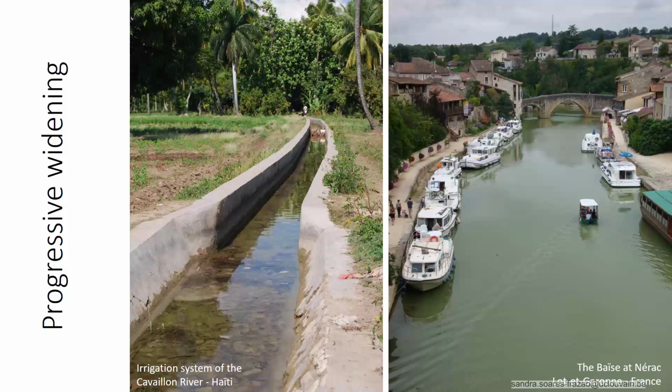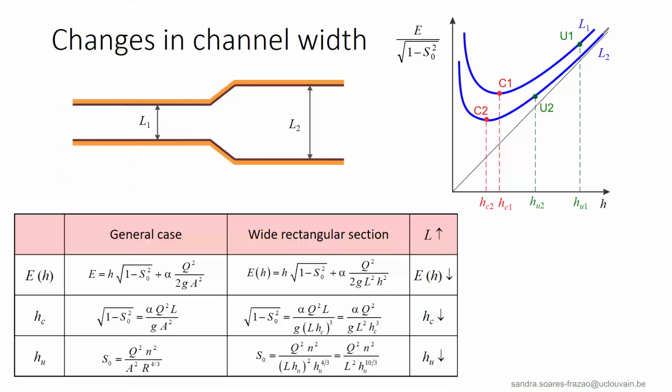Let us now consider a progressive channel widening. We can do the same analysis as the one conducted for a channel narrowing, and conclude in the present case that for a width L2 larger than L1, the specific energy for a given water depth will decrease, as well as the critical and normal depth. This is illustrated here on the specific energy diagram. We have the curve corresponding to L2 that is below the L1 curve.